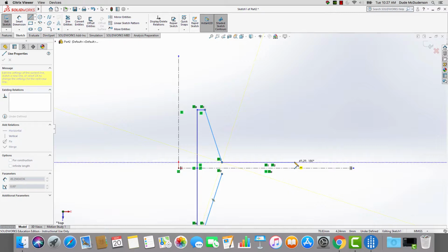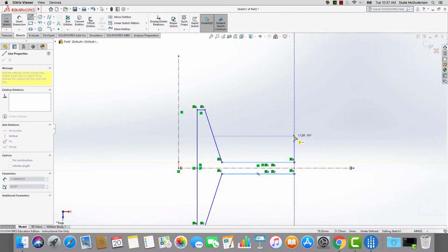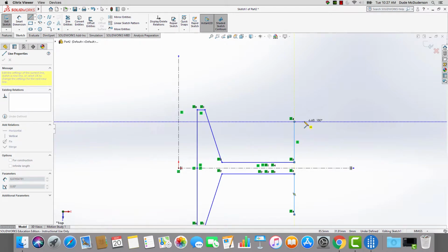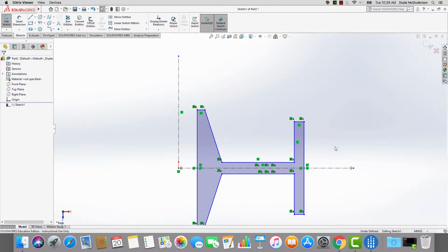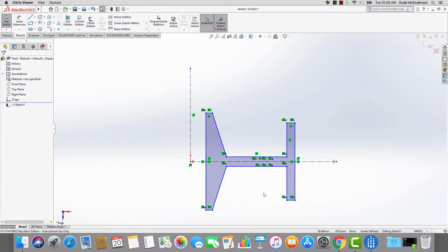And you can see that because the dynamic mirror line is on, every time I click, it's actually creating a line below that mirror line for me. So I can see the resulting geometry. So I pulled another vertical. I'm pulling now a short horizontal. And then I'm going to finish this off by going down and stopping at that midpoint line. Again, it's important not to cross over that line because then it lays a line on top of itself. So you want to stop right here on that mirror line and finish that off. The minute I click there, obviously I've created a solid closed body. It's turned gray, so it's indicating that that's a closed body. And I have kind of the start of my wheel.